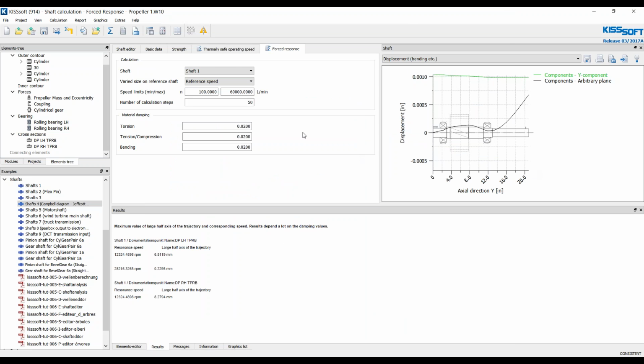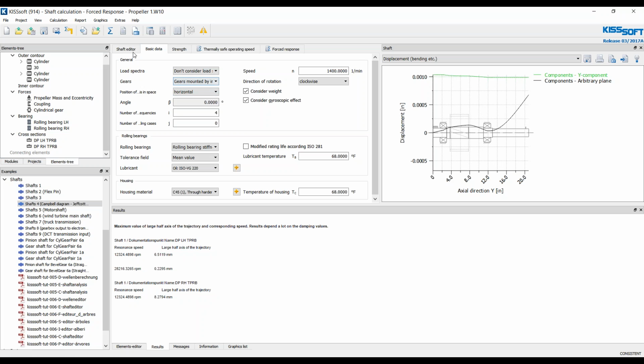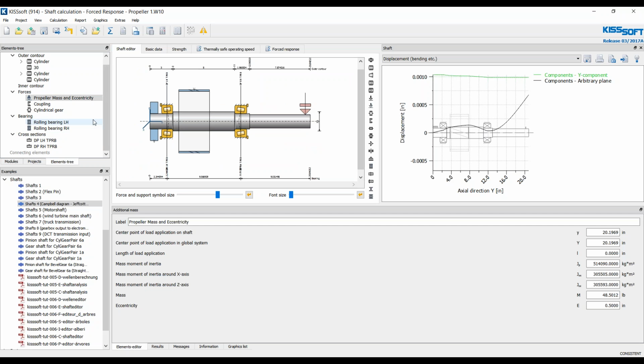Make sure when you're working with this, you're putting your imbalanced mass out here for your calculation. And you can see here in your displacement, this mass is being taken into account. So this guy here weighs, oh, what does it weigh? 48 pounds in this particular example.